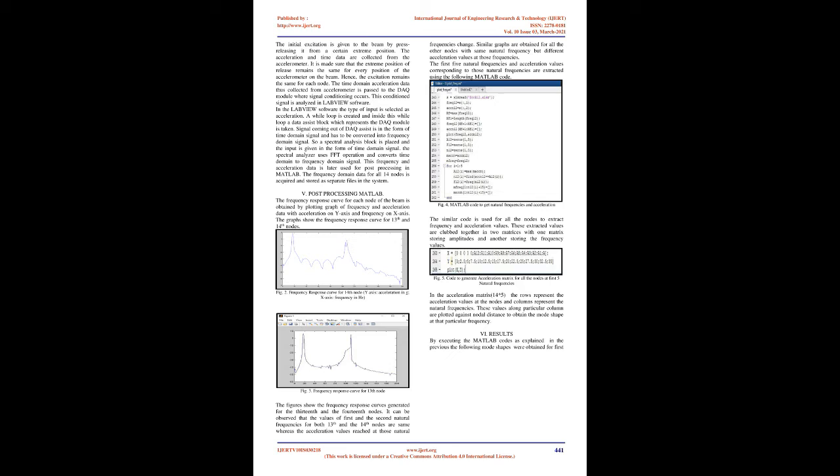An experimental approach to free vibration analysis of smart composite beam, G. A. Yashwantha Kumar and K. M. Satish Kumar. The numerical study of the free vibration analysis of the smart composite beam by using ANSYS is explained in this paper. Here the author has conducted the analysis on a composite beam made up of glass epoxy, and PZT patches are added on the surface of the beam. Then the vibration analysis is carried out under the clamp-free condition of the beam.